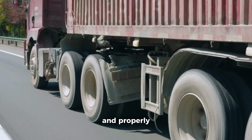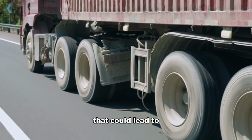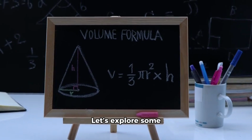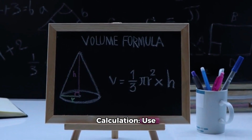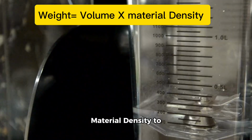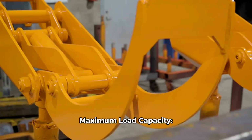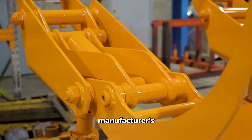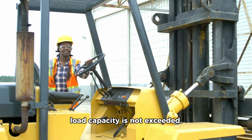Load calculation and weight distribution. Calculating the weight and properly distributing it is vital to prevent overloads that could lead to equipment failure or accidents. Let's explore some basic calculation methods. Weight calculation. Use the formula weight equals volume times material density to determine the weight of standard loads. Maximum load capacity. Always refer to the manufacturer's specifications to ensure the equipment's maximum load capacity is not exceeded.